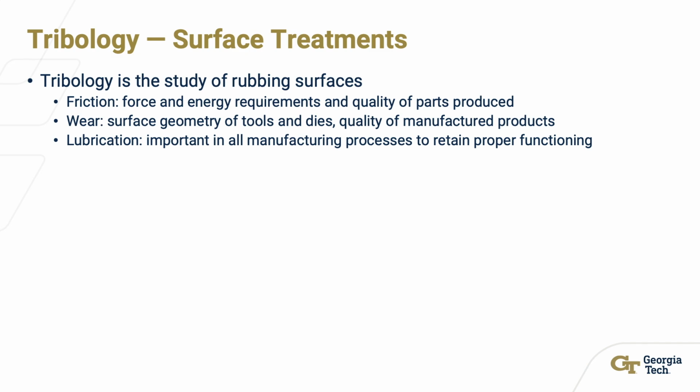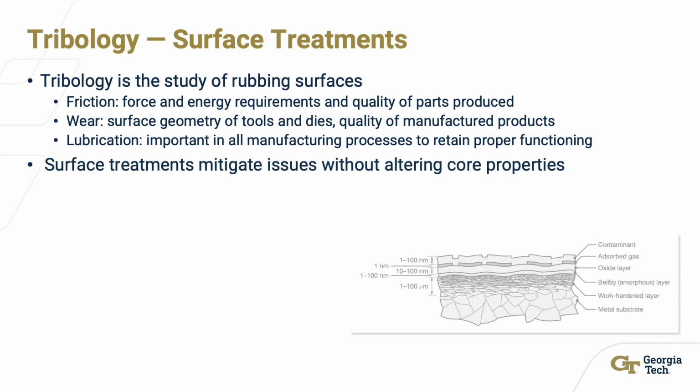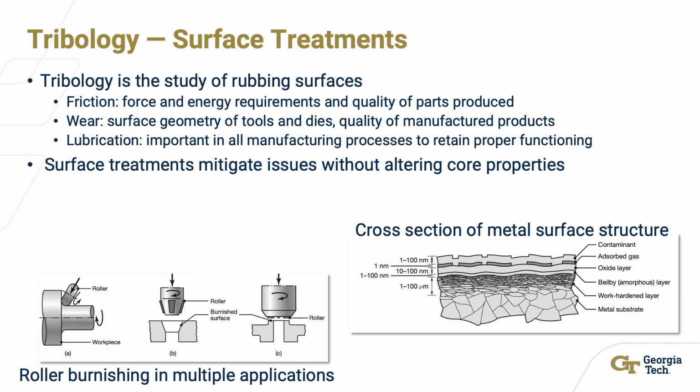These factors can all be better controlled through the use of surface treatments, especially to improve performance. Surface treatments may be applied to enhance surface smoothness, appearance, dimensional precision, and frictional properties, increase resistance to wear, erosion, and indentation, manage friction between contacting surfaces and tools, dies, bearings, and machine components, boost resistance to corrosion and oxidation, improve fatigue strength, especially in bearings and shafts, or even add decorative features, such as color or unique surface textures.